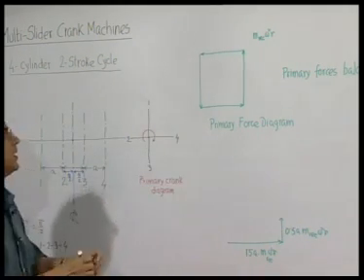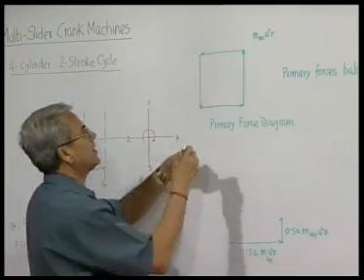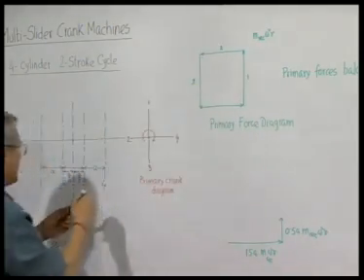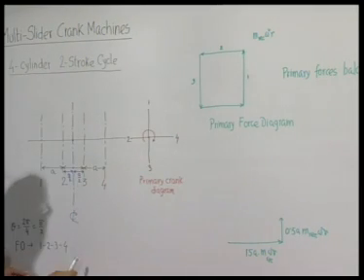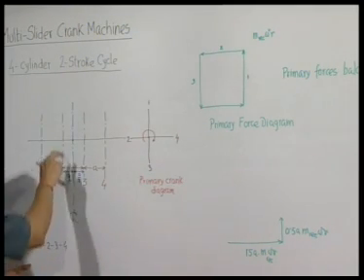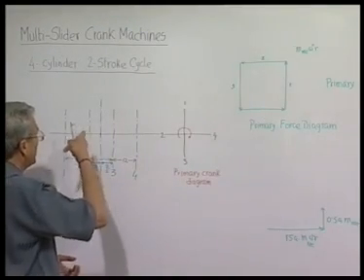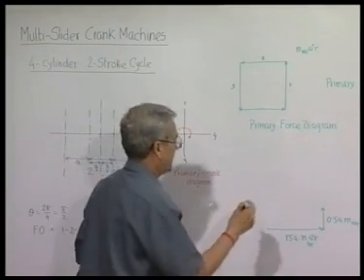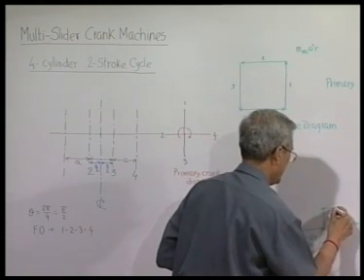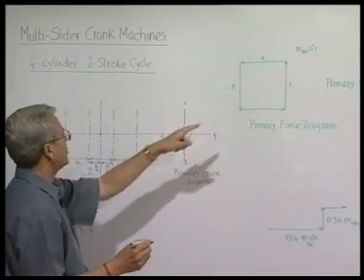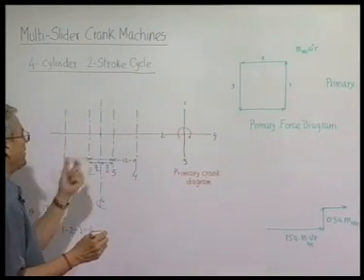Okay. Next comes, this is cylinder number 1, cylinder number 2, cylinder number 3. Now, cylinder number 3 is here, the force is coming in the downward direction. That means this force will produce another moment in this direction, and its magnitude will be again the same as this, m reciprocating omega square r into 0.5 a.